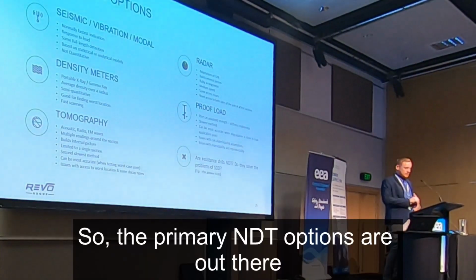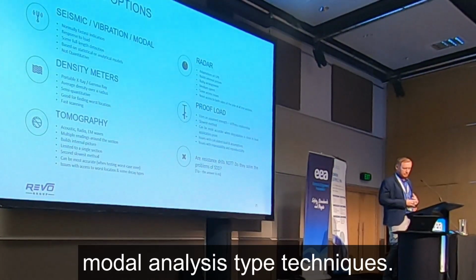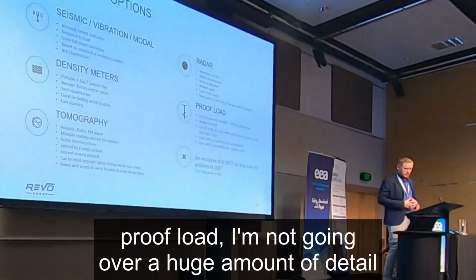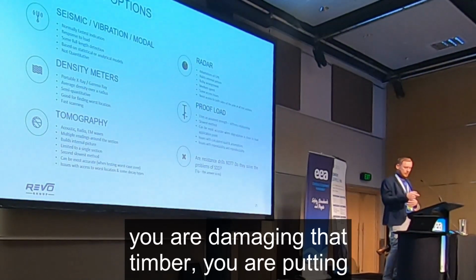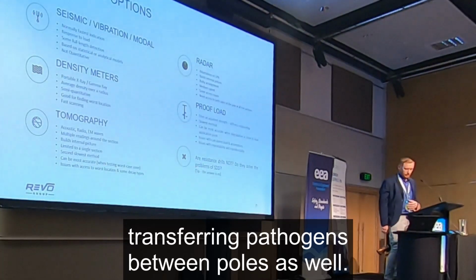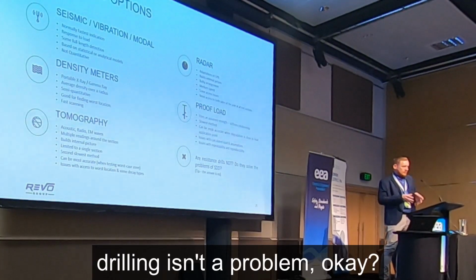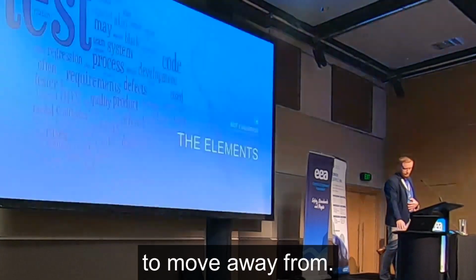So the primary NDT options out there in terms of categories, you've got the seismic, vibration, modal analysis type techniques. You've got density meters, tomography, radar, proof loads. I'm not going to go into a huge amount of detail about them. The one thing I will say is resistance drilling is not an NDT technique. You are damaging that timber. You are putting a potential pathway for pathogens inside that timber, and you're potentially transferring pathogens between poles as well. It's just a better way of drilling. Drilling is your problem. That's what you want to move away from.